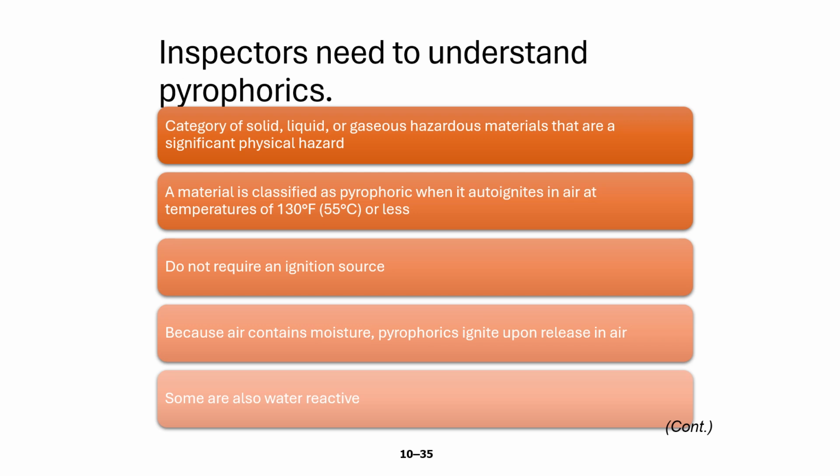Reason being, the air contains moisture, and pyrophorics ignite upon releasing in air. Some pyrophorics are water reactive. So very unstable, the controls to make sure that the material is used appropriately or stored appropriately is pretty significant.